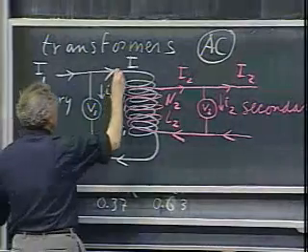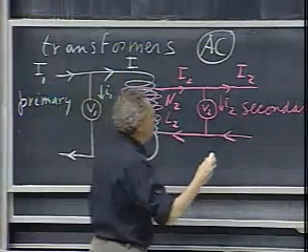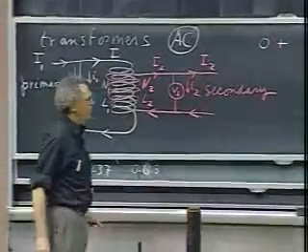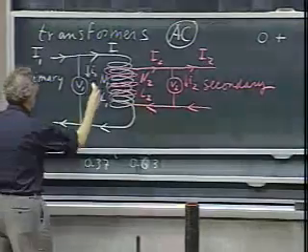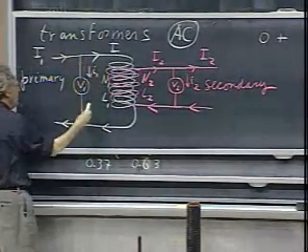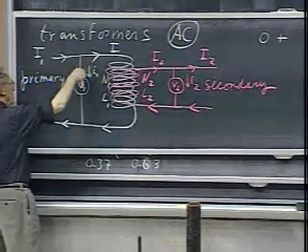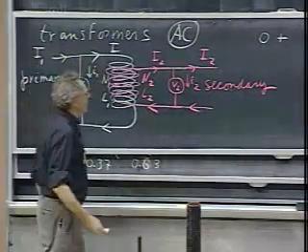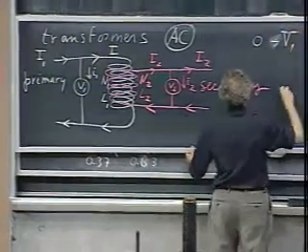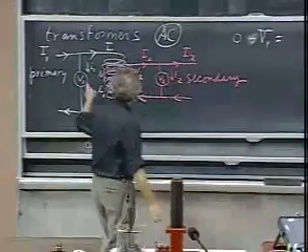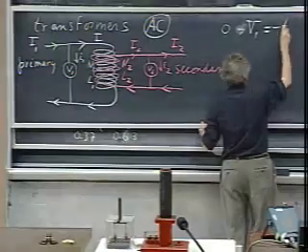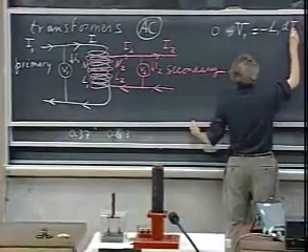And so if I start here and I go through the self-inductor, I know there is no electric field in the self-inductor, so that contribution of E dot dl is 0. Then I arrive here at this current, which is opposing me. I go in this direction, but the E field is opposing me, and so I get minus V1. And that now, according to Faraday's law, since I went in the direction of the current through the self-inductor, equals minus L1 di1/dt.